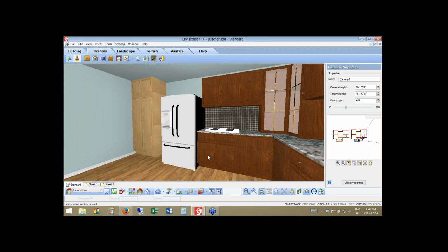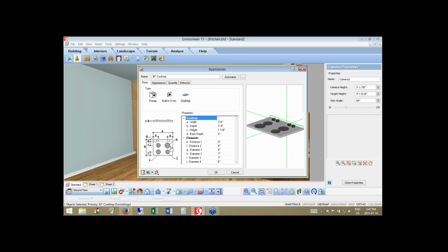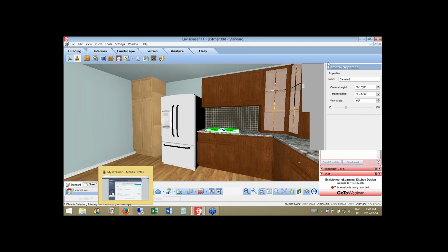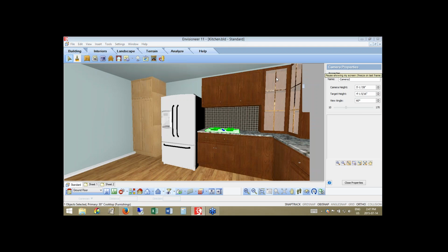If you are familiar with SketchUp, and perhaps you want to use some blocks you find out on SketchUp, maybe a custom one, maybe you know the exact element, what it's supposed to look like, you don't want to just alter our block itself. So right here you can see how I can change the width, the depth, and give it that generic look. If you wanted it to be precisely what you had in mind, you can always go up to the Google 3D Warehouse. So I'm just going to go out to the internet right now.